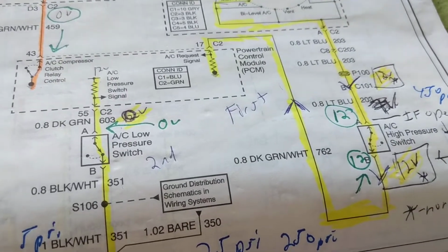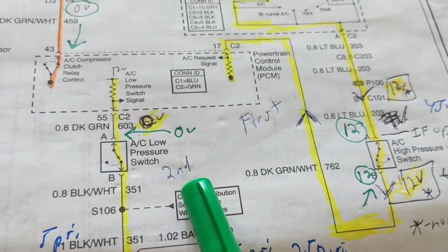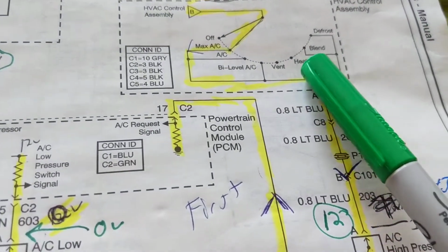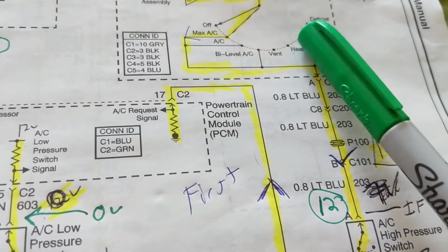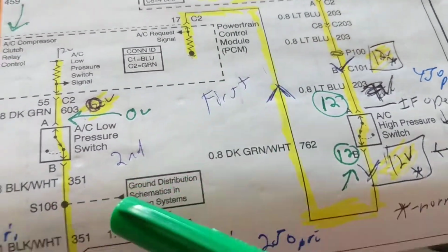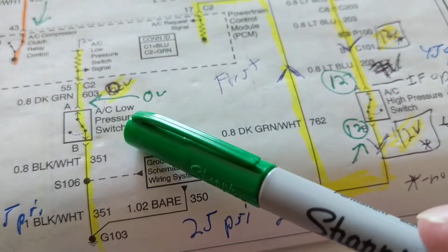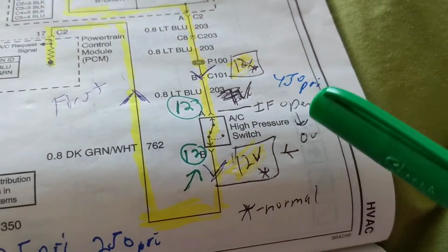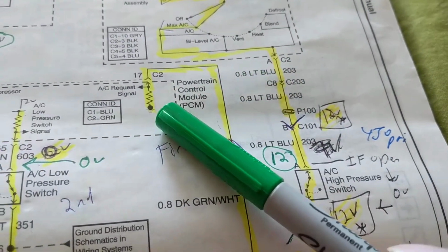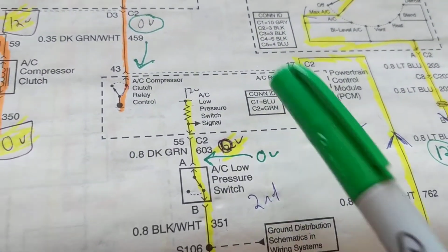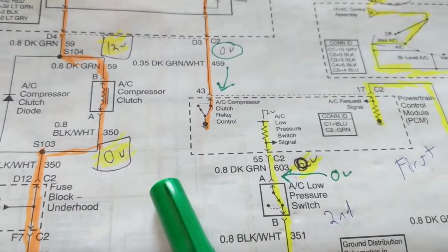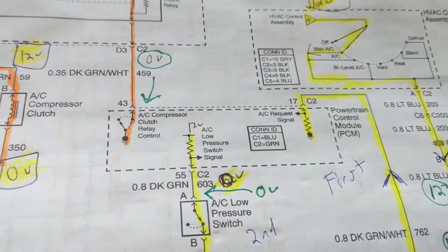Now, I think there's a misconception in troubleshooting AC. Like I said, the first thing is no cold air. I'm going to put on defroster. I want to see if even the defroster has it. If defroster doesn't have it, that means the compressor clutch is not engaged, or there's a computer problem, or a low pressure switch, instead of being closed, is open, or a high pressure switch is in the other position, open, not allowing this. Right? It might be a computer problem, or this was not grounded by the computer, or the relay is not activated. Not just the clutch, and not just the compressor.